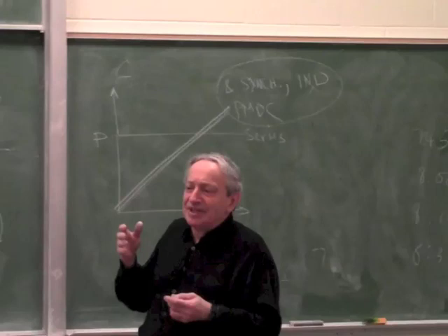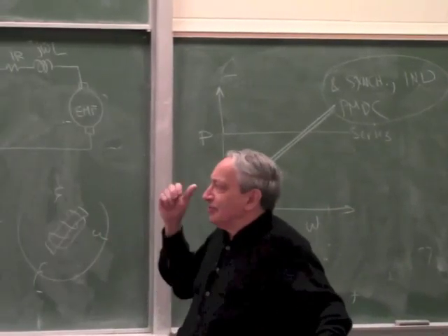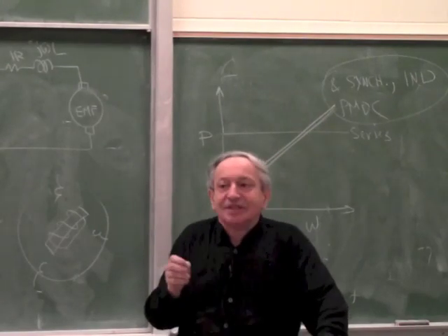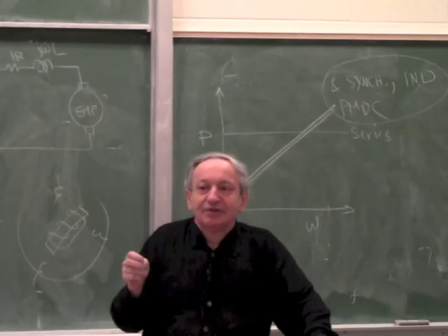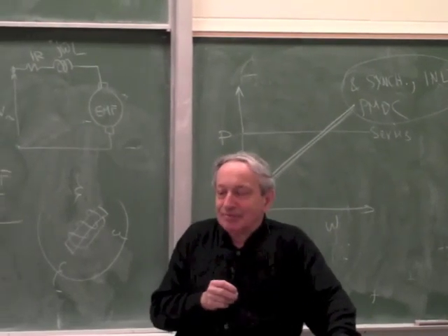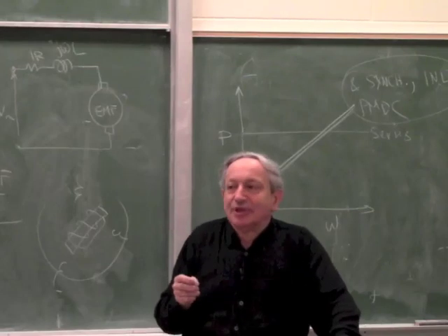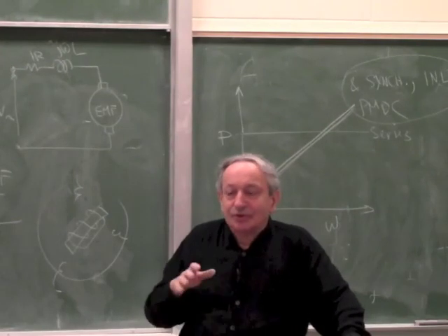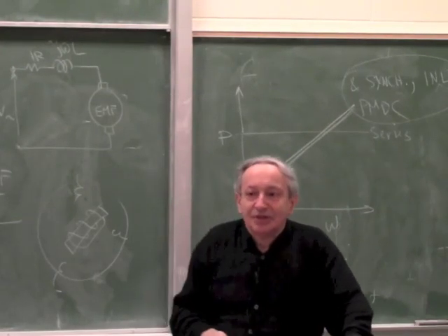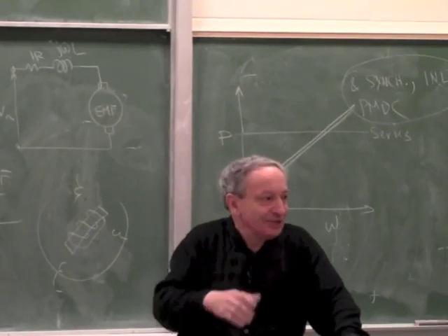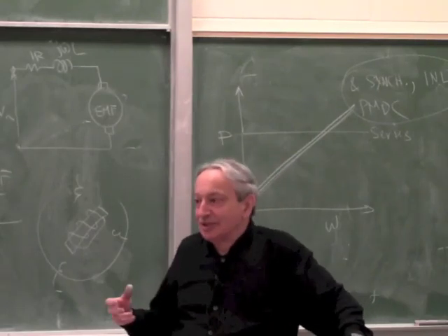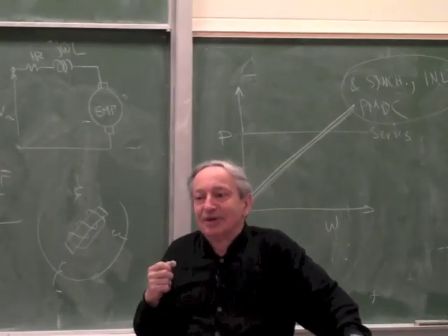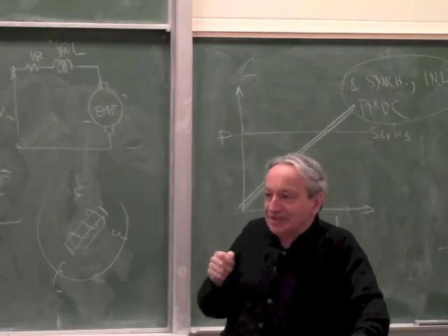As I mentioned, I gave you the analogy that a series motor, which gives constant power, is equivalent to a motor which has the ideal automatic transmission. Because the purpose of an automatic transmission is always to match the power of the motor to the load. So if you have a regular car, when it starts, you go to a low gear, because you need a lot of torque at low speed, so you have to gear down a lot, so you can use all the power of the engine. And as you speed up, you gear it down less and less, but you're trying to always get the maximum power. A series wound DC doesn't need that.